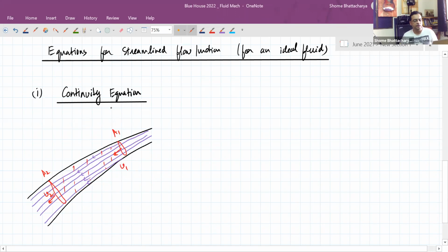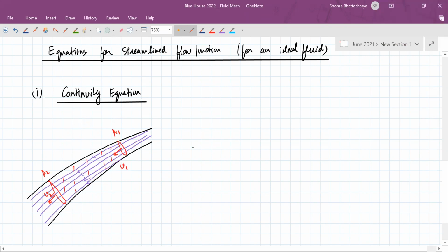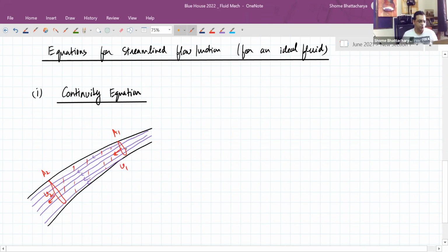The important thing is the continuity equation will tell us the relationship between V1 and V2, and it will express that relationship by going back to the fundamental property of streamline motion and the fact that it's an ideal fluid. The liquid molecules are moving in pure translation through this section because it's irrotational motion, and they are moving in such a way that there is no turbulence. So there's no sudden change in pressure because of collisions and all that.